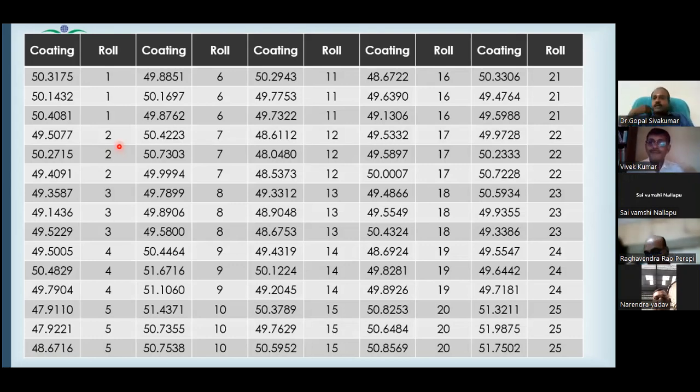The machine operator himself will run the business. The company doesn't require a data expert and all. But now the tolerances are too small. We require 50 plus or minus 0.3. So within batch variation, if you don't monitor, if you don't control, there is a chance that the entire lot might go wrong. Hope all of you agree with me. Yes, sir. Total 3,000 will get rejected.